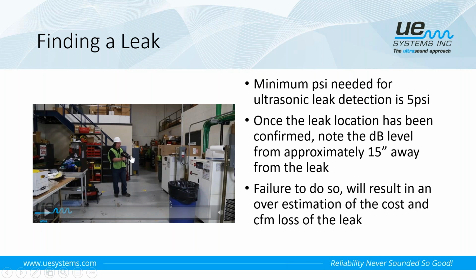So you notice here that we're standing back several feet away, and we teach this as the gross to fine method. So you've already heard me talk about the sensitivity adjustment and how that's a way to narrow down the field of view or to block out competing noise. So we can start our survey from several feet away from our equipment, and we're going to scan the area left and right, up and down,